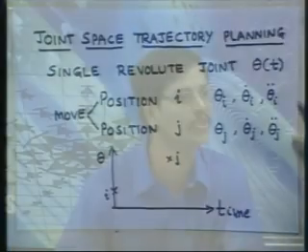If we are able to analyze this problem, then we will see that the overall motion of the individual joints creating the final end effector's motion is a case of fitting a series of such points i, j, k, l, m, n, and so on and so forth. And for each set of points, the motion between them can be planned through a particular smooth trajectory that we generate using this type of an understanding, and you can use several such segments of motion to get the total motion from the initial configuration to the final configuration.